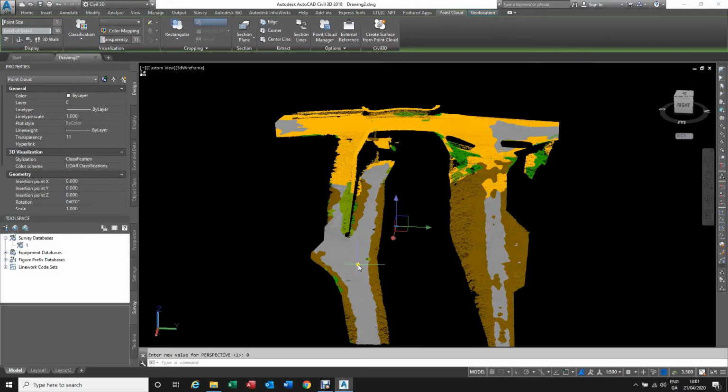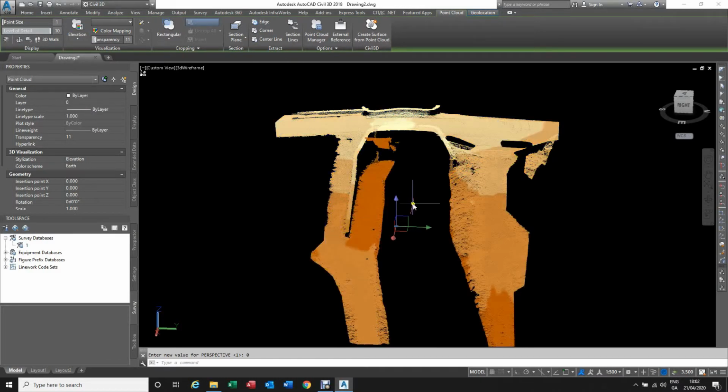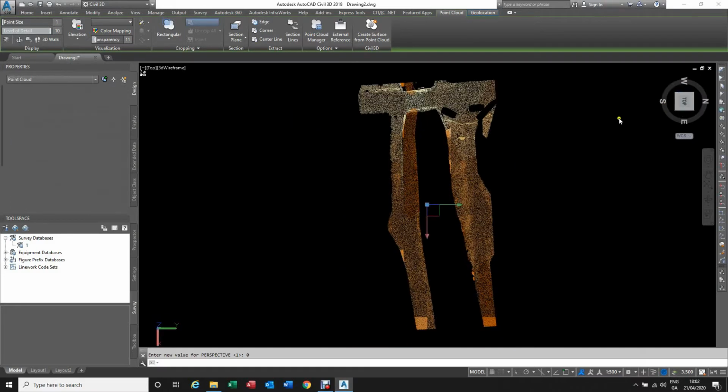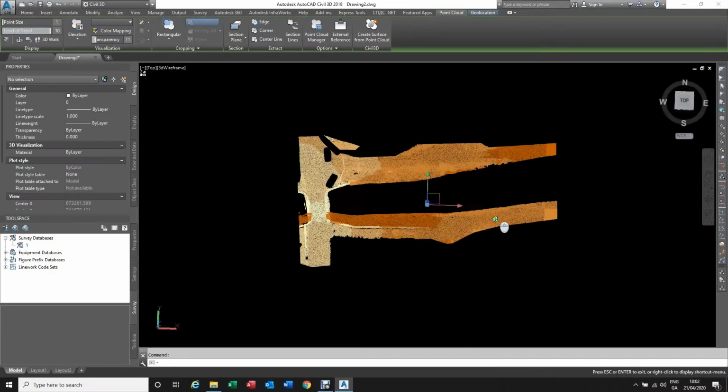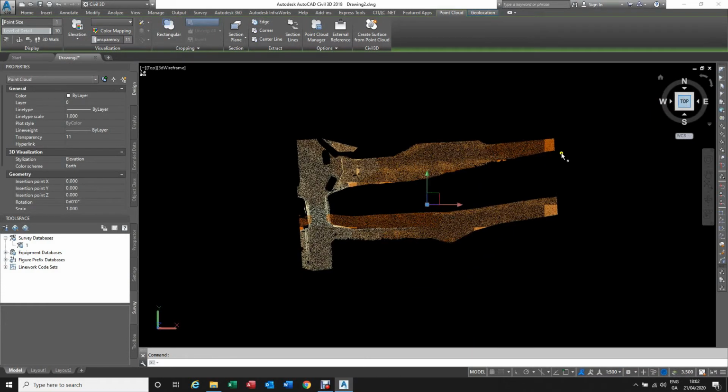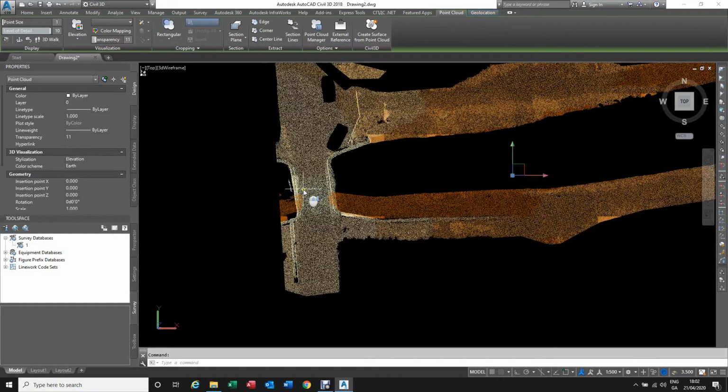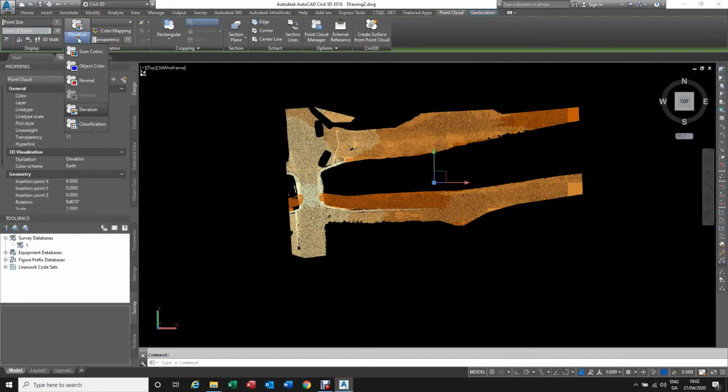That would mean if you classify a point cloud, the program sometimes automatically classifies that if it's a horizontal surface, that's most likely a road or something, or if it's very noisy, sometimes it's vegetation. So you can switch on and off those parts, so you don't have to manually clean things. It's not really a classified point cloud, so you can use elevation point cloud. Then even from top view you see which part of the point cloud is higher or lower. That's one thing you can use.